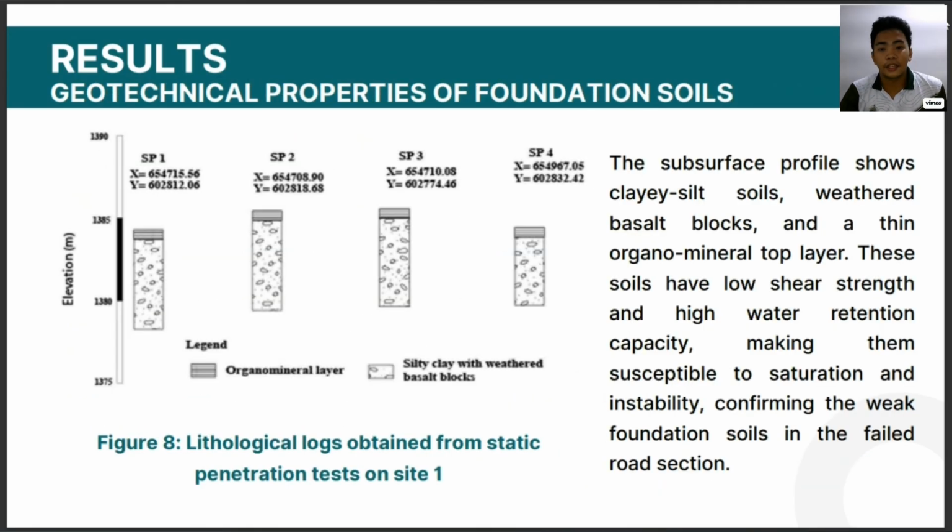Next is the geotechnical properties of foundation soils. Figure 8 shows that the subsurface profile consists of clayey silt soils, weathered basalt rocks, and a thin organo-mineral top layer. The penetration test shows soft, heterogeneous materials near the surface, transitioning to more competent layers at different depths.